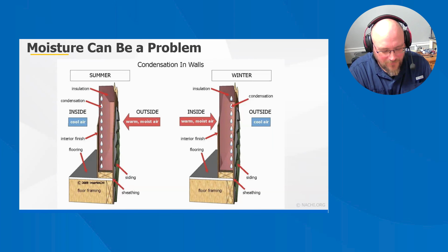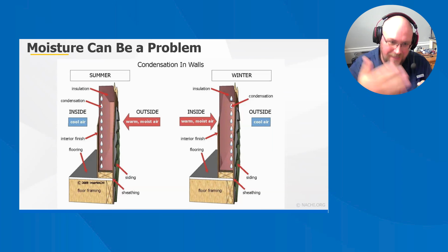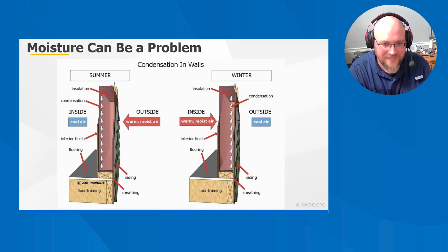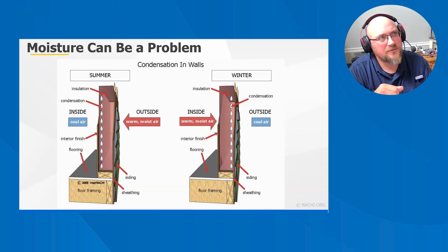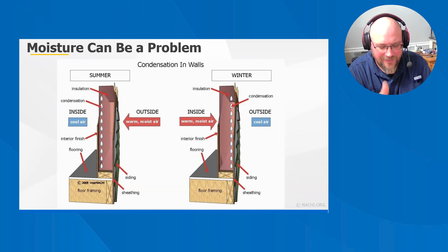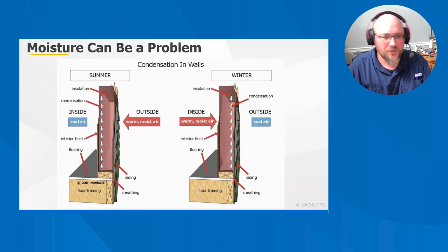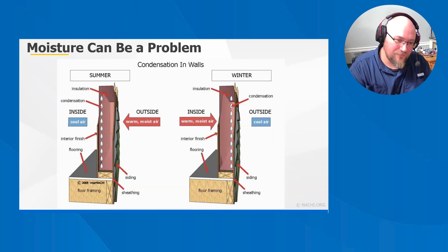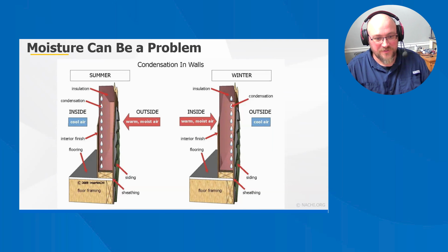They had weep holes in that foundation wall that did not have a rope or any plastic insert. It was just a hole. Well, no, I think the vertical mortar line of that brick was just exposed for the height of that brick, right? And so we were getting that super cold Arctic air blowing in. We think it was blowing in through the weep holes, and it was making the interior of